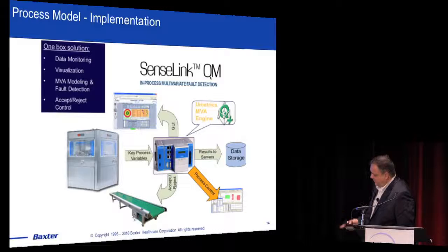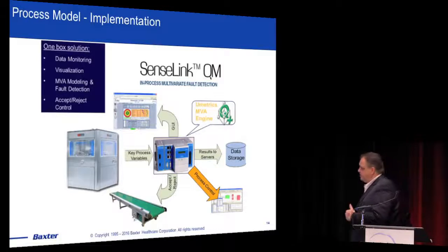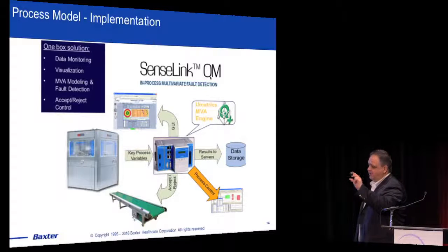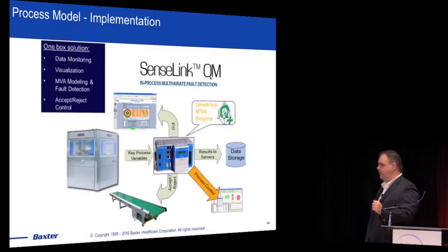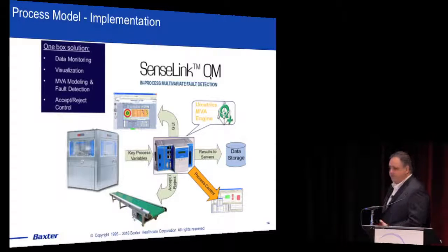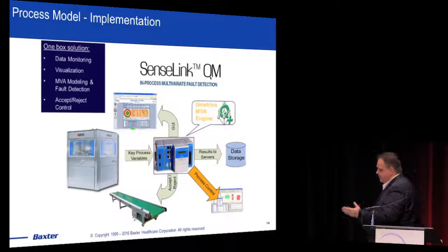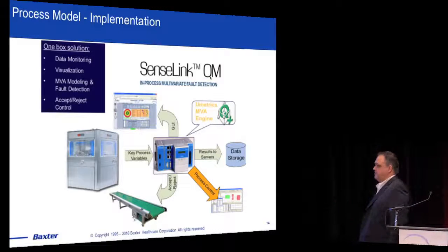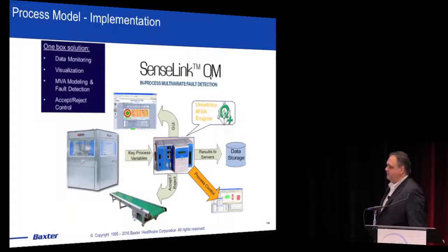We use it for molding machines, and it's very simple in terms of the control. We're not actually adjusting our process. We found it more efficient to do an accept/reject signal. So if the calculations come back and say this particular cycle looks different, rather than trying to compensate for that, we simply throw those components away. Then we have a control structure: if you have X number of rejects in a row, we're going to get somebody involved. But typically for the process upsets we're talking about, it's more cost effective and economical for me just to trash it automatically and move on.